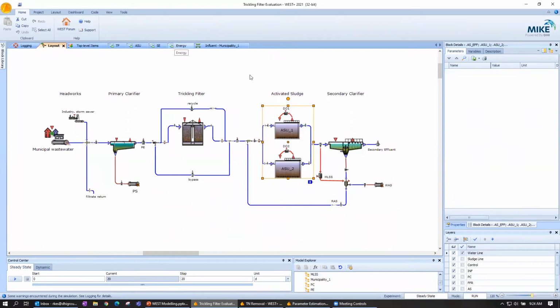Well, we had an aeration energy calculator, but these are just small DO controllers. They're not actually controlling a blower in this case. So we're working under the assumption that there is sufficient blower capacity for this job. And that's something that we're going to have to evaluate. That's not a fair assumption. We can make it for now and run this test, but we have to keep that in mind.